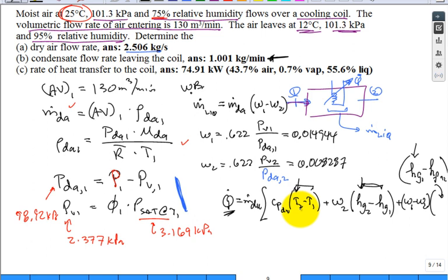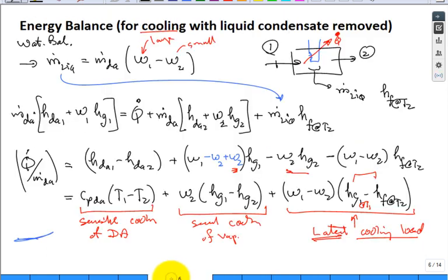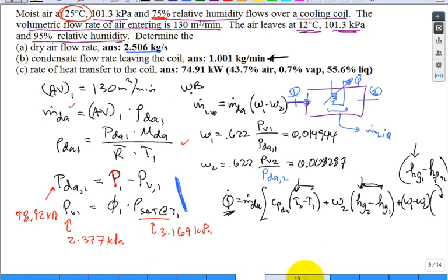Oh, I have a typo on the previous page. This page? Oh, look at that. Hold it. I messed up then. I'm sorry. This is coming in at a higher temperature, leaving at a lower temperature. Coming in at a higher enthalpy of the vapor, going out at a lower enthalpy of the vapor. Hot coming in at a higher vapor enthalpy, going out. Okay, thank you very much. I think he helped fix my error. True? 5 points. 5 points. On the final.